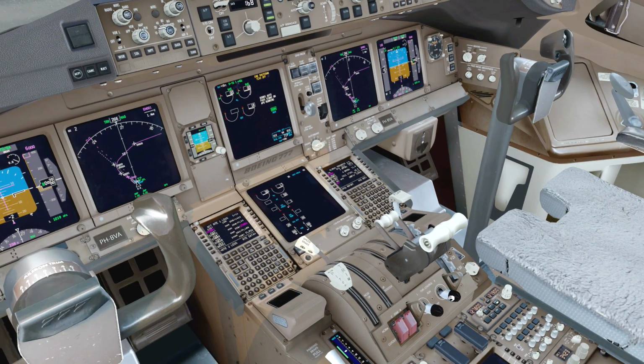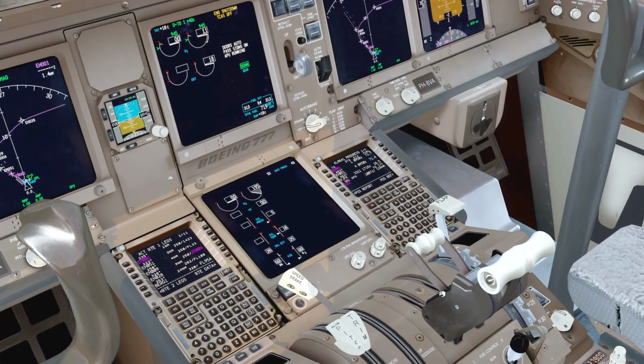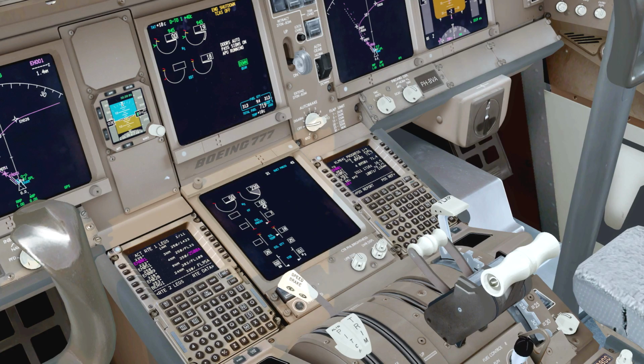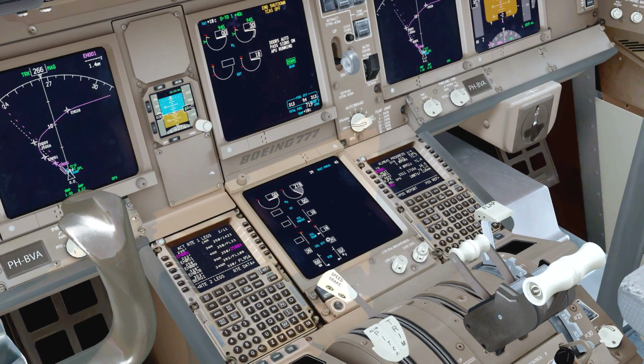As you can see, some parameters run up, and we're going to put the fuel control switch right on. Alright, so right now we just want to monitor these two displays, okay? Just make sure everything is okay. The aircraft will handle the fuel injection and all that stuff itself. Just make sure the engine vibration stays within limits. Oil quantity should be okay. Oil temperature. You need to make sure that you see some N1 rotation. In this case it seems to be working well. N2 is really spooling up right now.